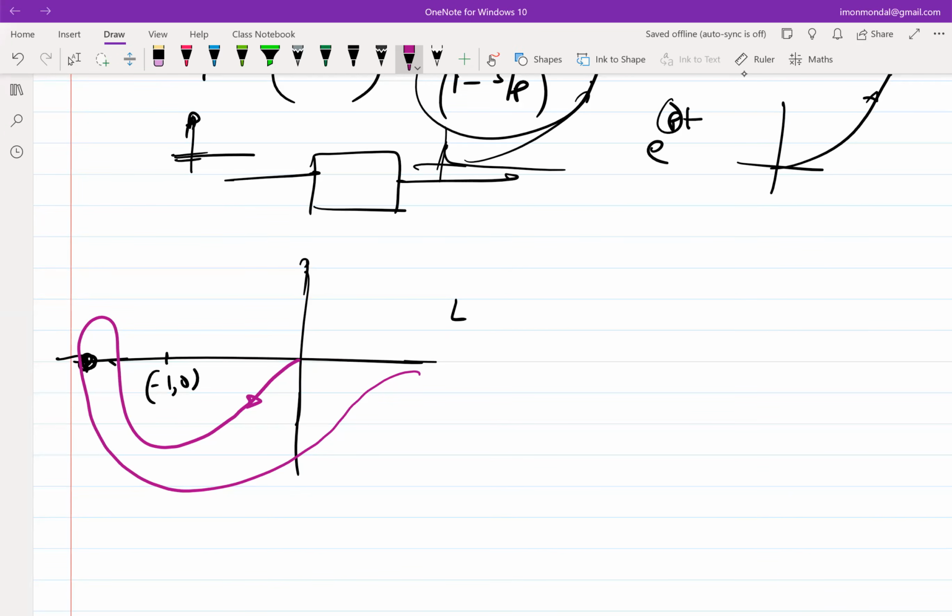And what am I looking for? I'm looking for encirclement. Why am I looking for encirclement? Because if it's encircled, then I know that a root of the V0 over Vi, or the pole of the V0 over Vi, lies on the right hand. So now we have graduated from finding that -1, 0 point only to seeing whether a root exists on the entire right hand, anywhere in the right hand.